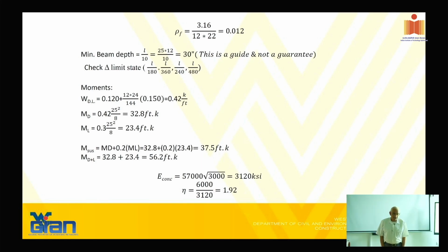Of the regular modulus to account for creep. You remember that? In that range, some people use 40%, some people use 33%, roughly 1/3. That is the creep deflection. So you are going to compute total deflection, including the creep, by reducing the modulus to 1/3. That's a good bit. I mean, that's an easy way to do it.